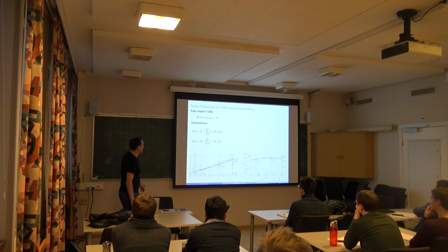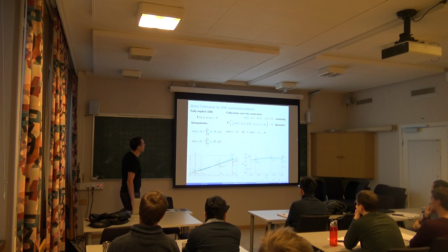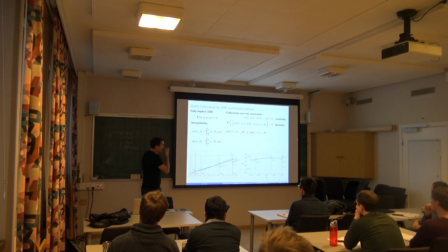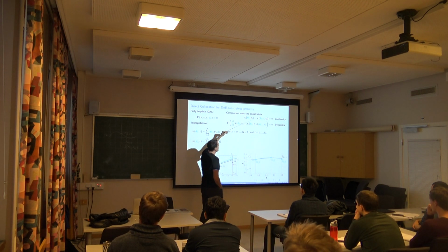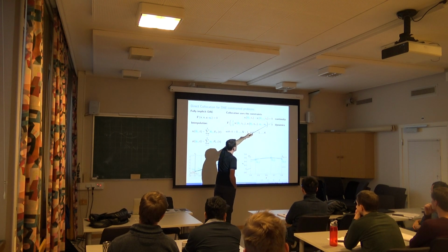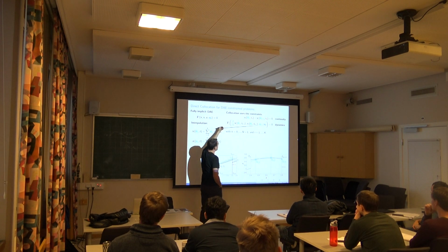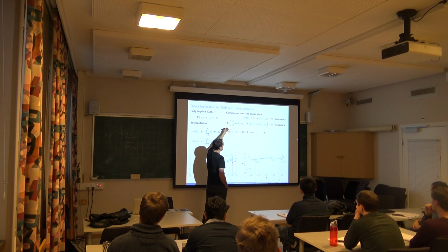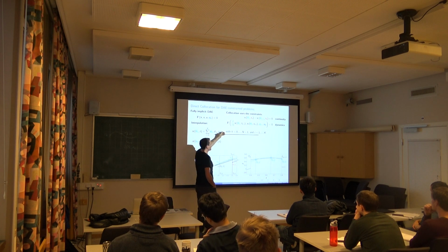Okay, so we have differential states, algebraic states, the interpolation scheme, and then the collocation constraint would basically look like this. You have a set of equations for enforcing continuity, that's the shooting gaps, and these constraints would describe or solve the dynamics of your DAE on the checkpoints.